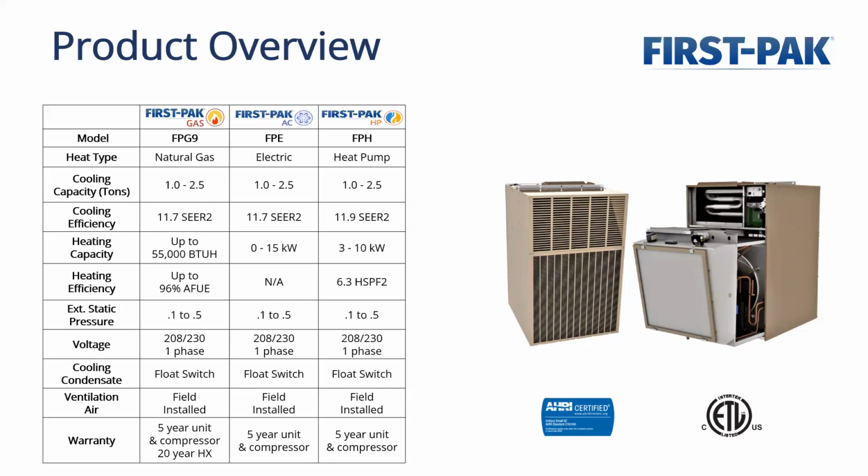So if the requirements are that you need to have some sort of backup or some sort of safety in there for if the condensate drain pan gets clogged or overflows, on this particular unit, we have that feature built in. All the ventilation air on these units is third-party field installed, and then we'll get into the Eco Series next, which has more of the integrated ventilation options.